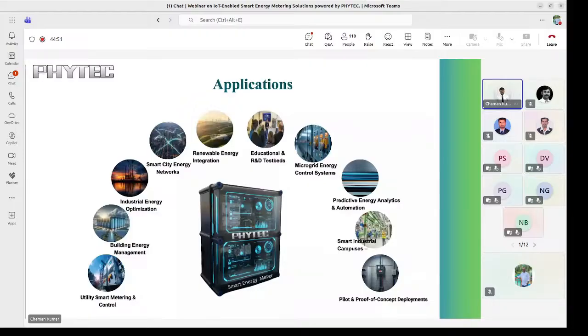Not only energy meters, any metering device, whether water meter, fire meter, or gas meter, follows a standard, the DLMS COSEM protocol, because it is interoperable. Any vendor who manufactures a meter has to follow this protocol. In India it came up as Indian standard 15959. Once you understand DLMS, it is basically a communication protocol for how the meter can communicate.